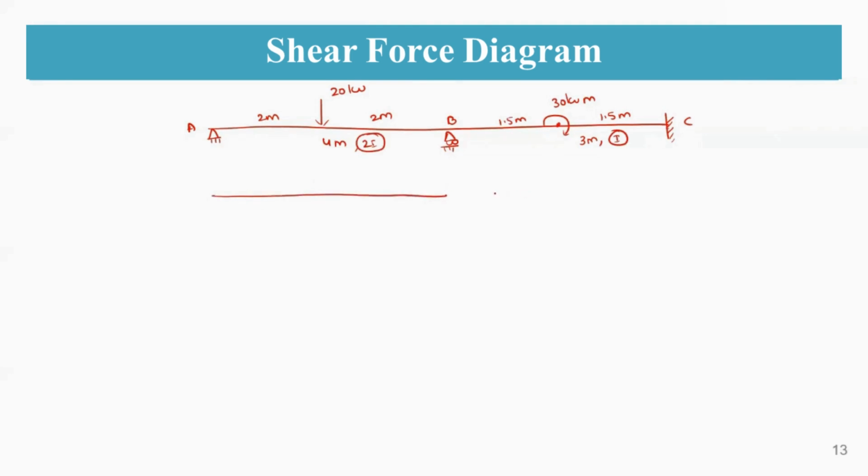So this is a free body diagram. So MAB moment is 0, and MBA and MBC moments are 11.03 kilonewton meter, whereas MCB moment is 5.73 kilonewton meter. So this is C. So now you're going to place your external loading, and then you're going to find out the reactions to draw the shear force diagram.